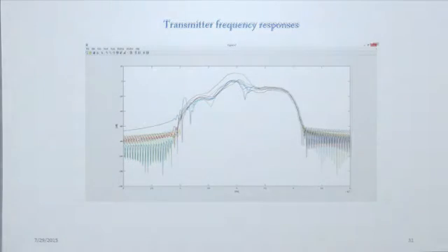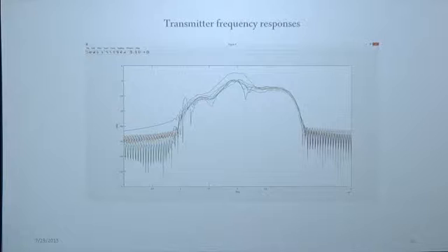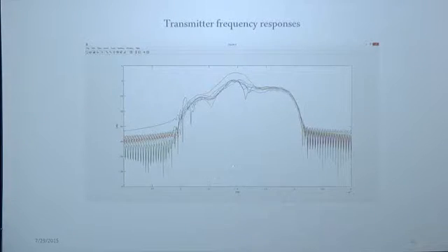One more challenge that we faced, by the way, this is after calibration. You can see that they are not very well matched. So this was something that created some delay in our progress, but of course you can see that the resonant frequency is somewhere close to 40 kilohertz. Actually, your work area is between 45 and 50 kilohertz. Yeah. This is where they match, and they're flat out of the resonances.